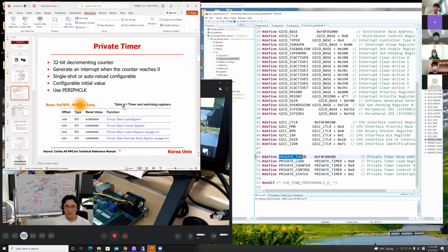You have to do this math, right? The timer takes the clock as an input. Then the prescaler does a division operation. In our example, we set the prescaler to 10.